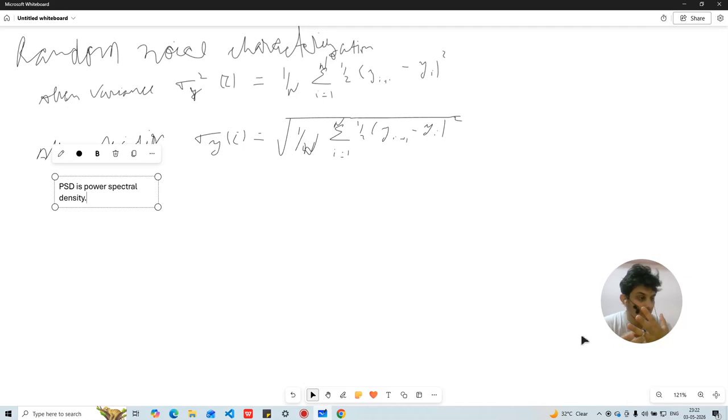Phase noise, power spectral density, PSD. Let's see what kind of noise is inside the signal. Think of noise like bass, low frequency, and treble, high frequency. Phase noise asks: at which frequency? Allan variance compares neighboring timing errors in the time domain.